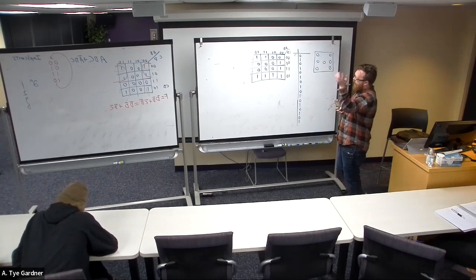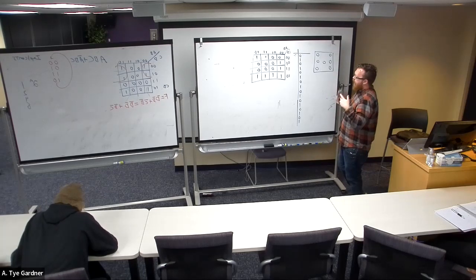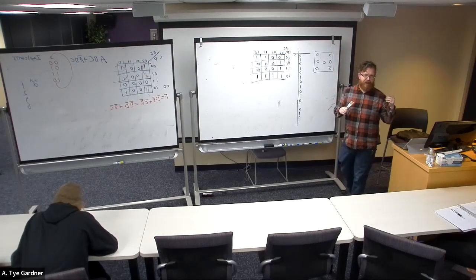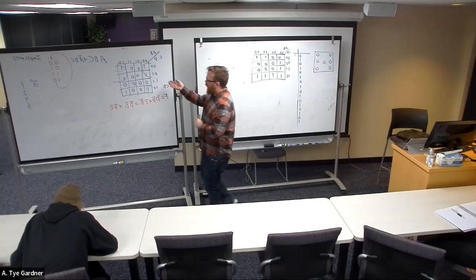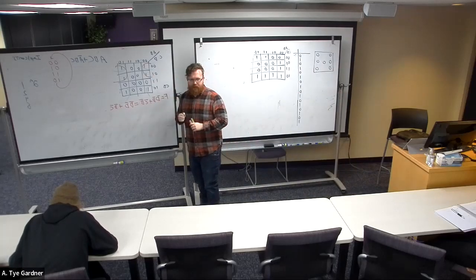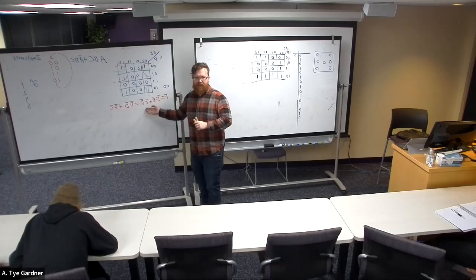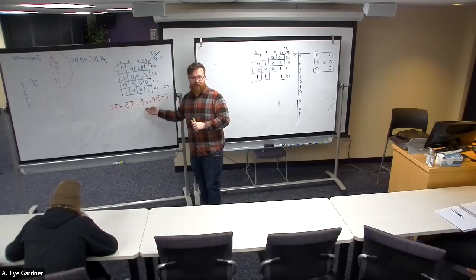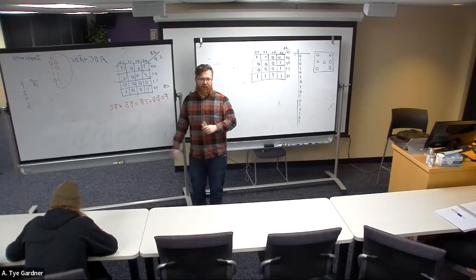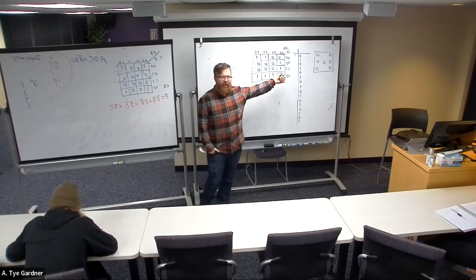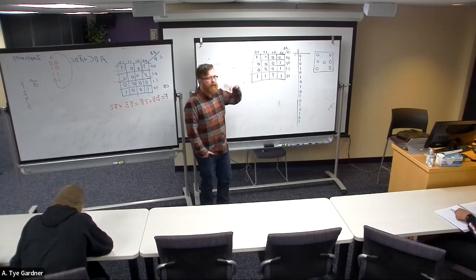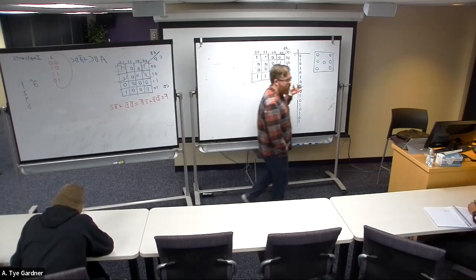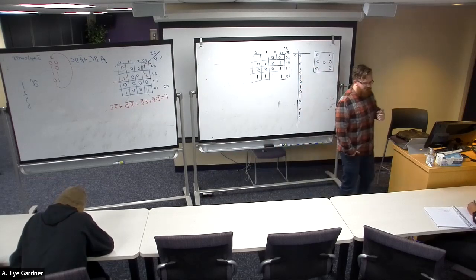Realistically, given a circuit, if you don't care if it's a NAND or NOR, this is actually what it's really doing for you: if I am circling the ones, I'm making it very easy to design a NAND-based circuit. If I am circling the zeros, I'm making it very easy to make a NOR-based circuit. This is how the K-map ties in very tightly to your circuit design.